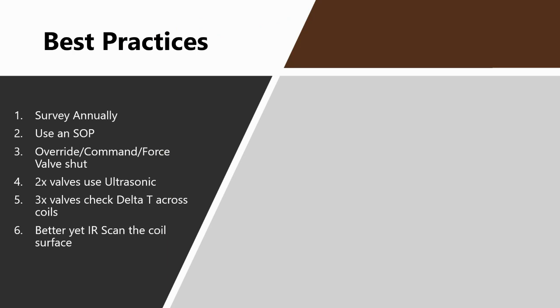Best practices used to avoid problems with leaky valves should include surveying for leaky valves annually. This is especially important if boilers and mechanical cooling are allowed to operate at the same time, as a leaky heating valve is oftentimes masked simply by the cooling valve right after it in an air handler. It will automatically just open up wider to overcome the heat that's being imparted into it from the leaky valve.